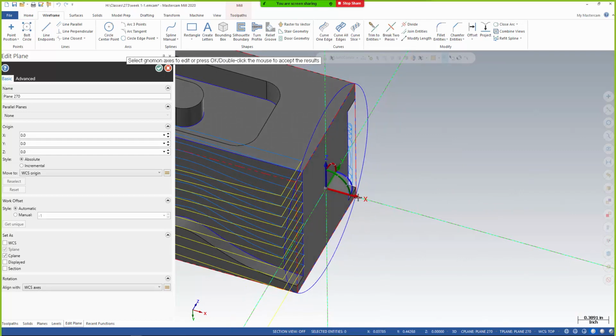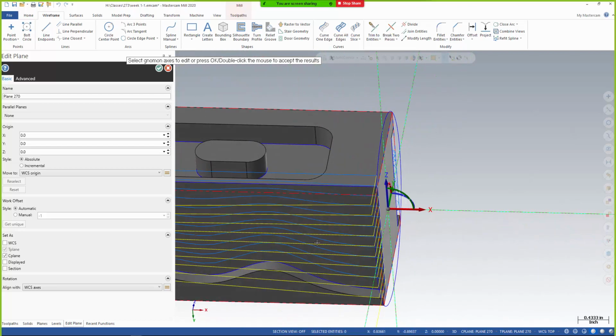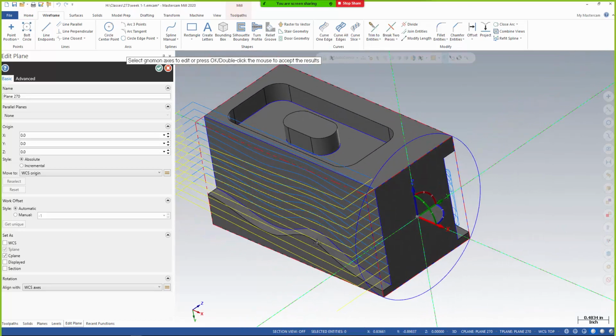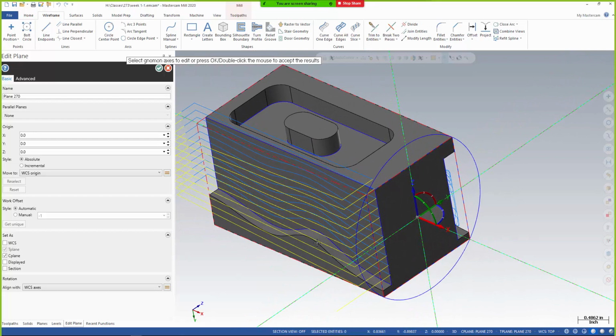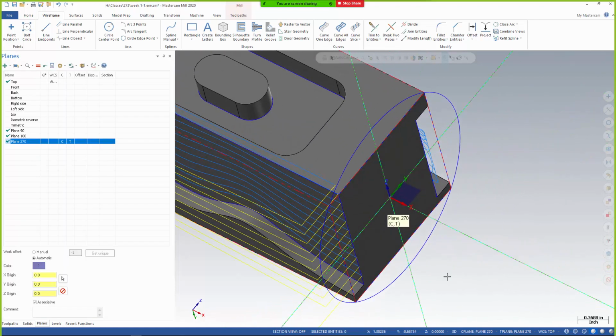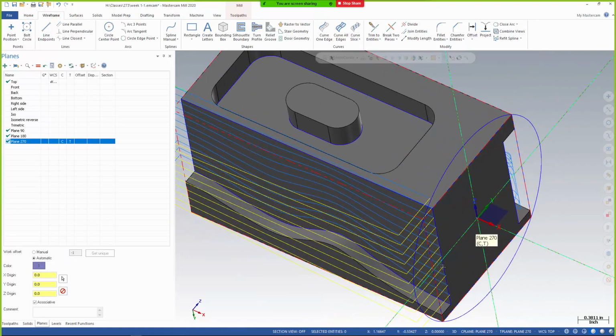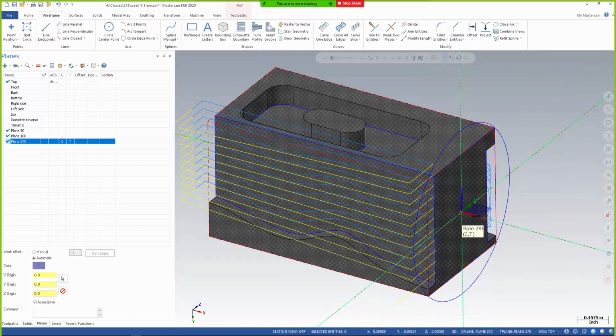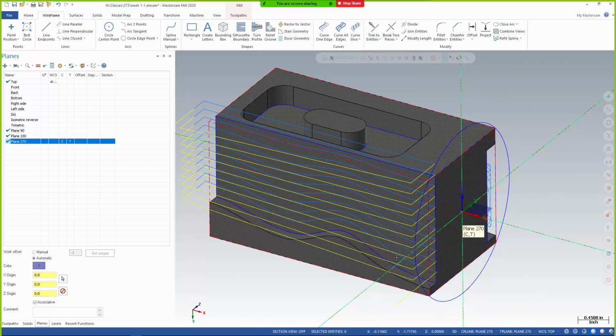Please pay attention to this. I can't tell you how critical this is. I had an issue one time on a 5-axis. This was actually a UMC 750 Haas 5-axis machine. They're actually fairly decent. I know you'll hear me bash on Haas quite a bit, but they're actually fairly decent. I had the x-axis pointing in a weird way, and the machine did not react the way I was anticipating. In other words, it looked fine in Verify.